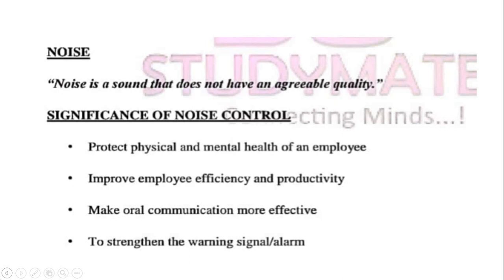That's how to control the noise. Noise can also be controlled by sometimes enclosing the machines, right? This is very important. And finally, the best method of noise control is at the source. This can be done by the manufacturer through engineering changes on the source itself, through regular maintenance, lubrication, and replacement of parts, or by changing the way materials are handled.